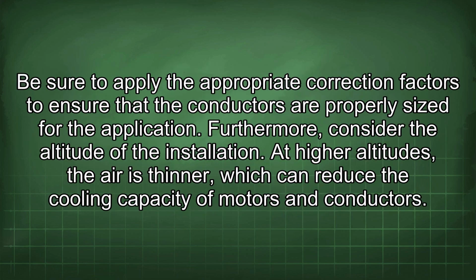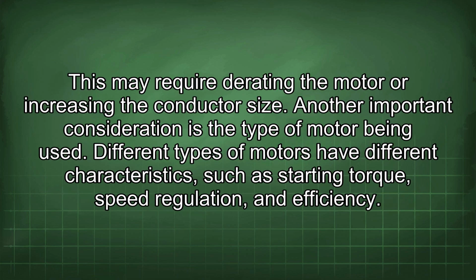Be sure to apply the appropriate correction factors to ensure that the conductors are properly sized for the application. Furthermore, consider the altitude of the installation. At higher altitudes, the air is thinner, which can reduce the cooling capacity of motors and conductors. This may require derating the motor or increasing the conductor size.